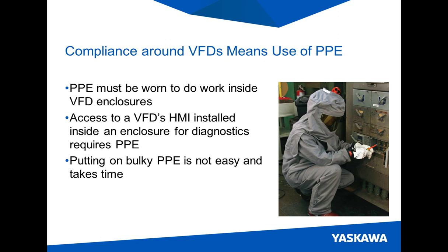So compliance to these arc flash standards means use of personal protective equipment or PPE. So putting on this clothing, as you can see in the picture here, to perform work on VFDs can be difficult and actually take a lot of time. And that's often the case when personnel have to open up a cabinet where the VFD is contained. And we care about PPE in this session because I'm going to be talking about some activities that we can do with a mobile app and Bluetooth that can reduce how often we must wear PPE.